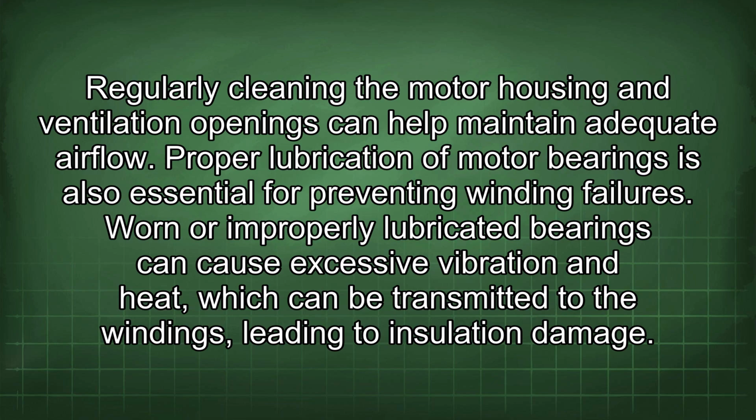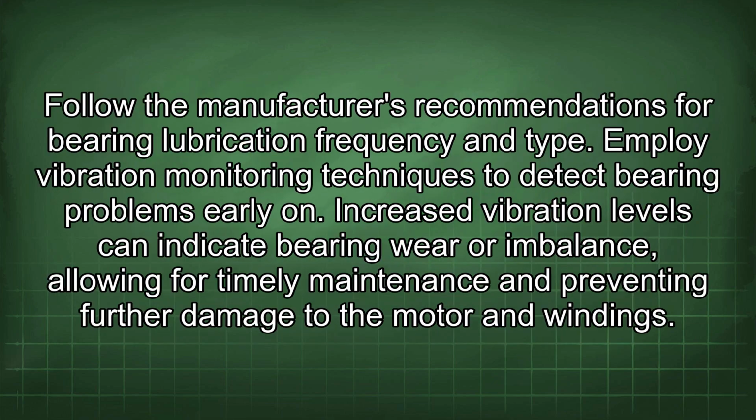Worn or improperly lubricated bearings can cause excessive vibration and heat, which can be transmitted to the windings, leading to insulation damage. Follow the manufacturer's recommendations for bearing lubrication frequency and type. Employ vibration monitoring techniques to detect bearing problems early on. Increased vibration levels can indicate bearing wear or imbalance, allowing for timely maintenance and preventing further damage to the motor and windings.